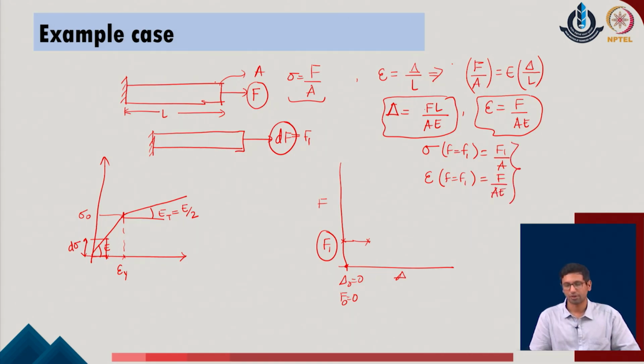Now, based upon the initial modulus, we will just try to calculate these two values of the given system, which means that we will evaluate the value of elastic modulus as the initial elastic modulus of the given system, and corresponding to that we can draw the simple profile. We can keep on drawing this profile till the point the system reaches the yield value of the given system, and as the system reaches the initial yield, we will modify the elastic modulus by the value of ET in the given system, and this way we can update the respective set of displacements which are obtained in the given problem.